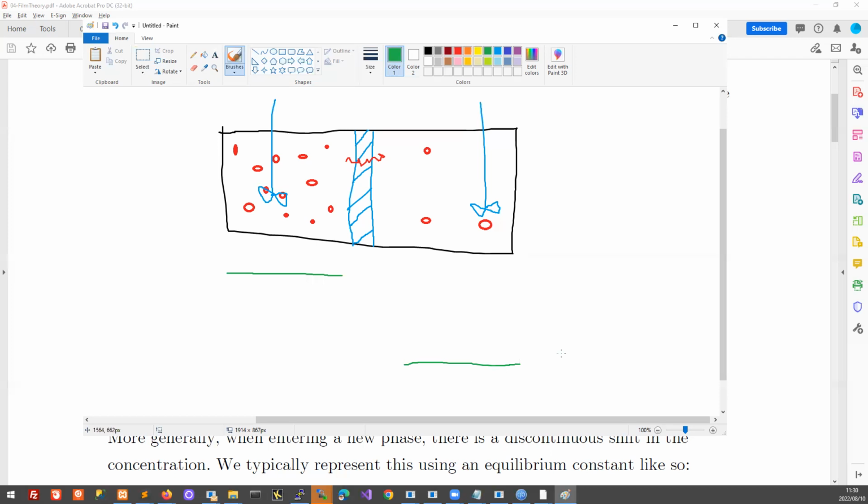And then it's still the case that A is going to diffuse across this permeable membrane. And because the concentration is low on the right side, the concentration of A will start dropping near the interface. And I just want to put the interface points down here also. Let's do it carefully. So there's the one interface. That's one side of the interface. And here's the other side.